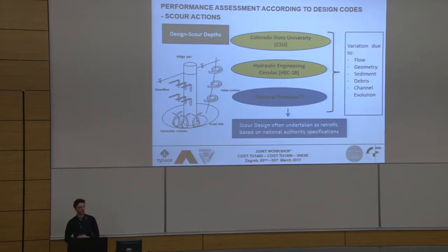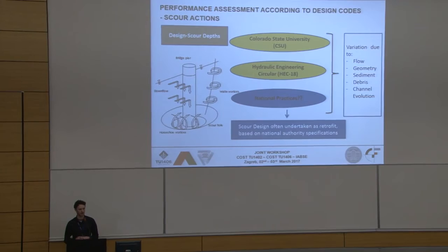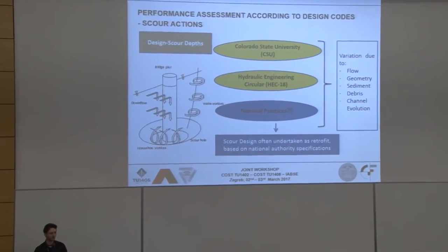But just on scour assessments due to design code compliance, scour has an effect at the design stage insofar as it is seen as a critical design scenario, so there are a range of methods used to design for it for a new construction. One of the findings of this paper was that there's a broad range of different design approaches used to design for a scour hole. I mentioned some of them there, like the CSU method or the HEC-18.